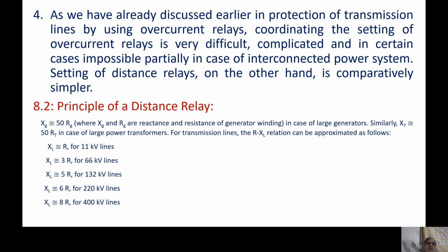Then, in doing that, another relay may have to operate very late. It has so often happened that for the fastest relay to operate just after 0.25 second, another relay has to operate 11 seconds later. That has happened.